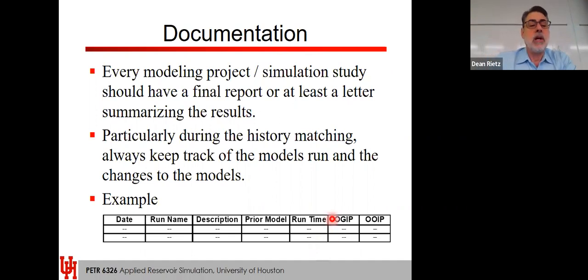Well, and then runtime, it's always good practice to keep the runtime. That runtime will be at the bottom of that out file. And usually it'll say 2 things. It'll be a CPU time and an elapsed time. CPU time is, if you're using a computer and others are using the same computer, that CPU time will be different than the runtime, because that CPU is being swapped out by other folks using that particular computer. I think you probably have dedicated computers on your models. You're running them on your standalone, so your CPU time is going to be very, very close to the runtime. So you want to keep track of that.